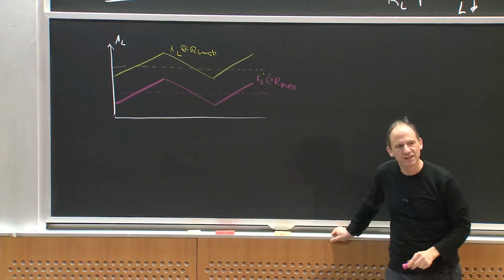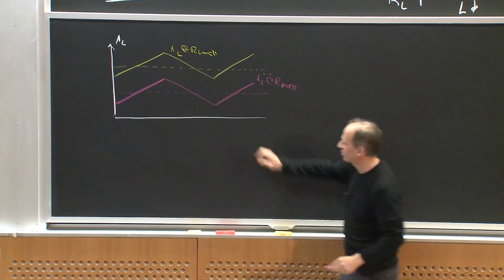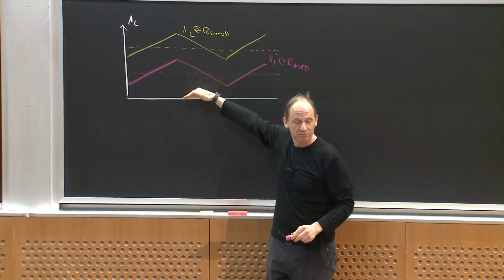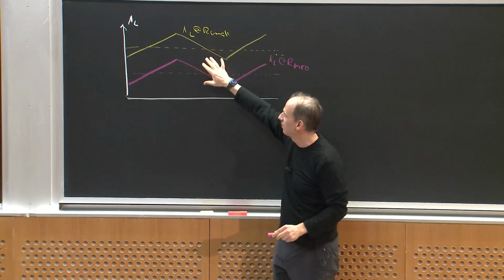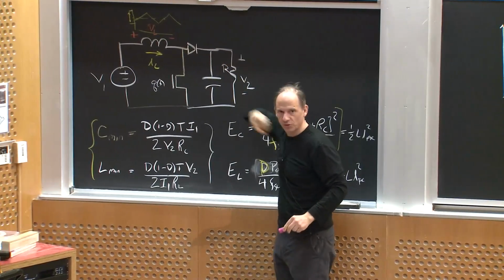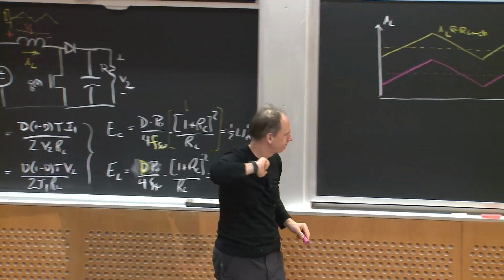What would happen if I kept increasing my resistance value? Well, all we saw is the waveform shape just doesn't change, the average just moves down, right? The ripple's the same, but the DC value is changing because I need more or less average current to support the output and more or less average power draw to support the output.